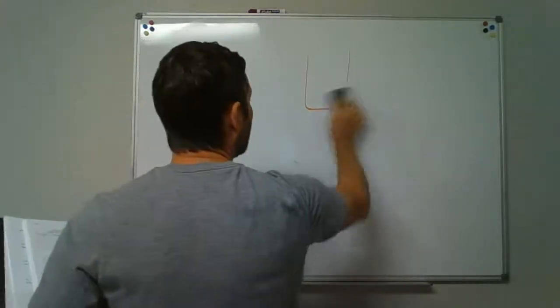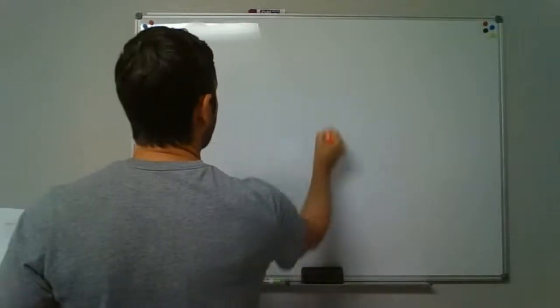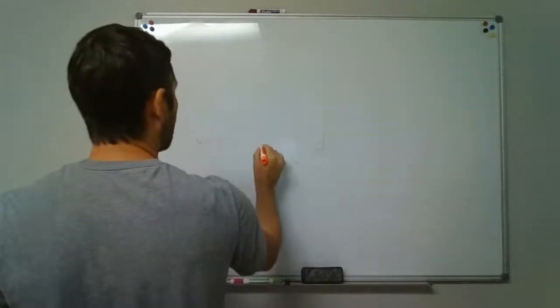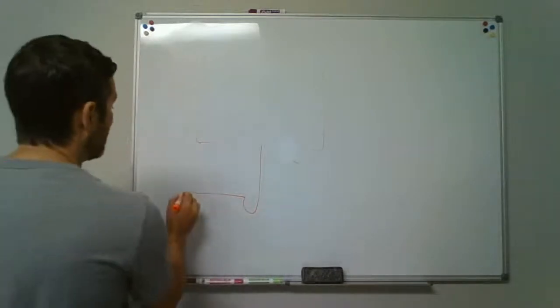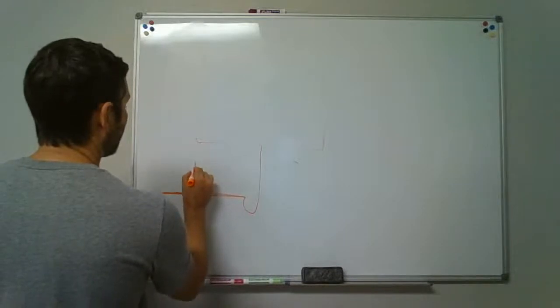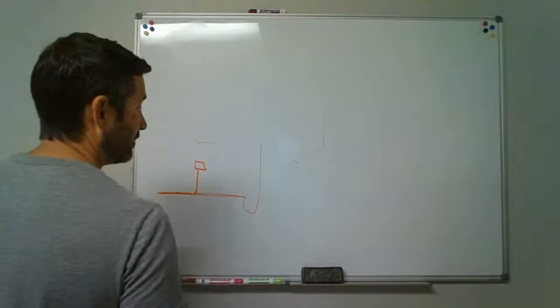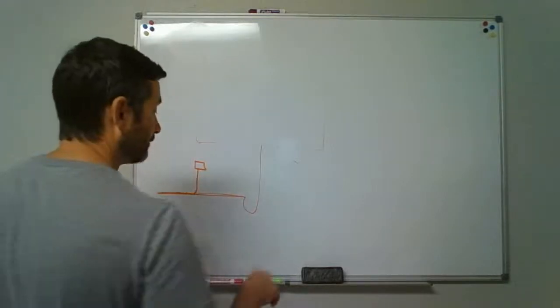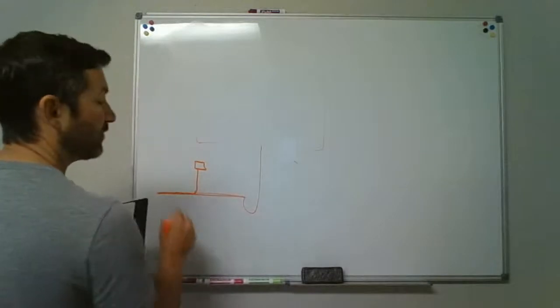So if you were underneath the house and said, "Man, I've got a shower, and I came down and put a trap, and I'm just adding in the shower or something." You say, "Boy, it's going to be tough to get a vent in there." Well, you could come up 4 inches above the fixture and put an air admittance valve underneath. You could have that underneath the floor if you need to. Another rule about those: that's going to be 4 inches up from there.